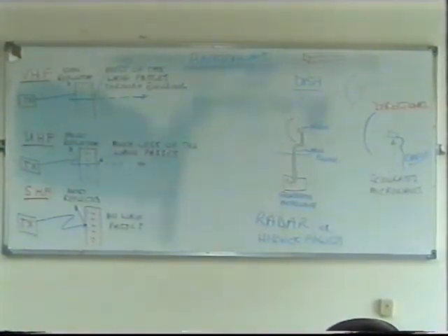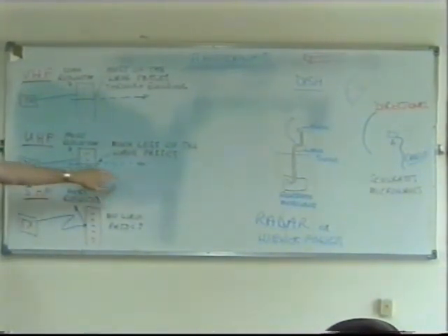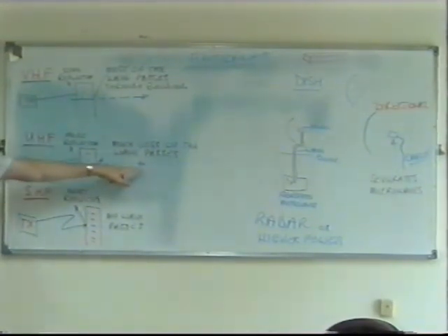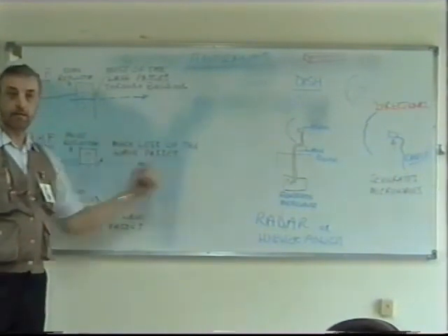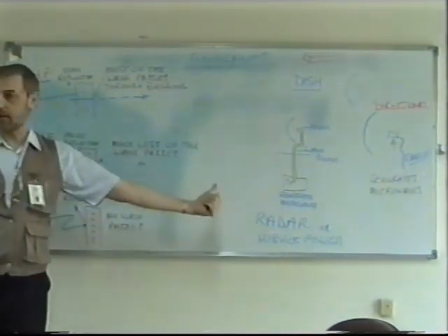And not only that, but because the wave goes through buildings, there's more likelihood you're going to interfere with one another if you're using the same frequency. Whereas at UHF, it's a little better. It's still not as good as VHF. We do get attenuation of the signal. If I have 2 buildings or 3 buildings here, then you probably lose your signal altogether.